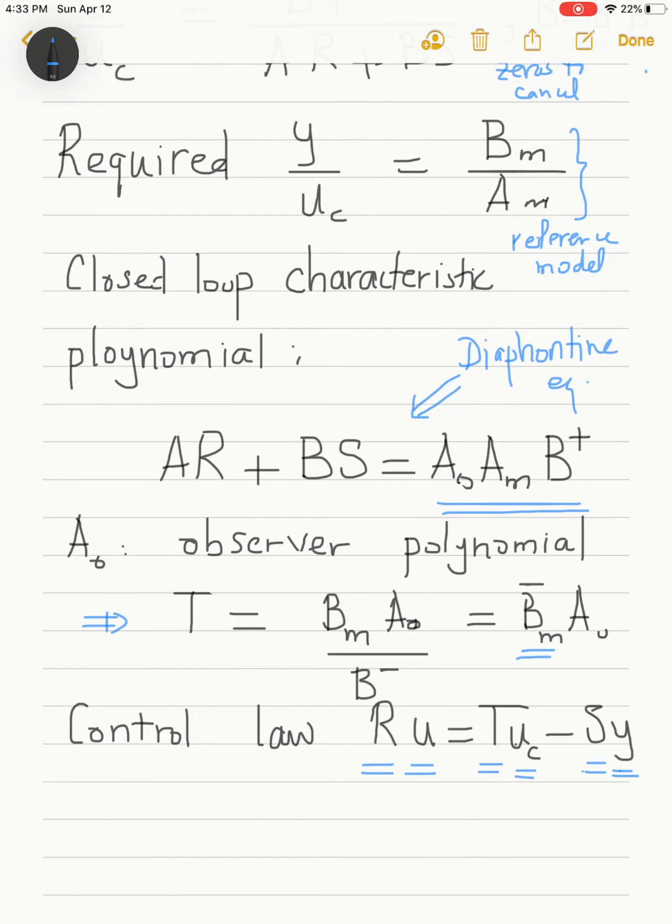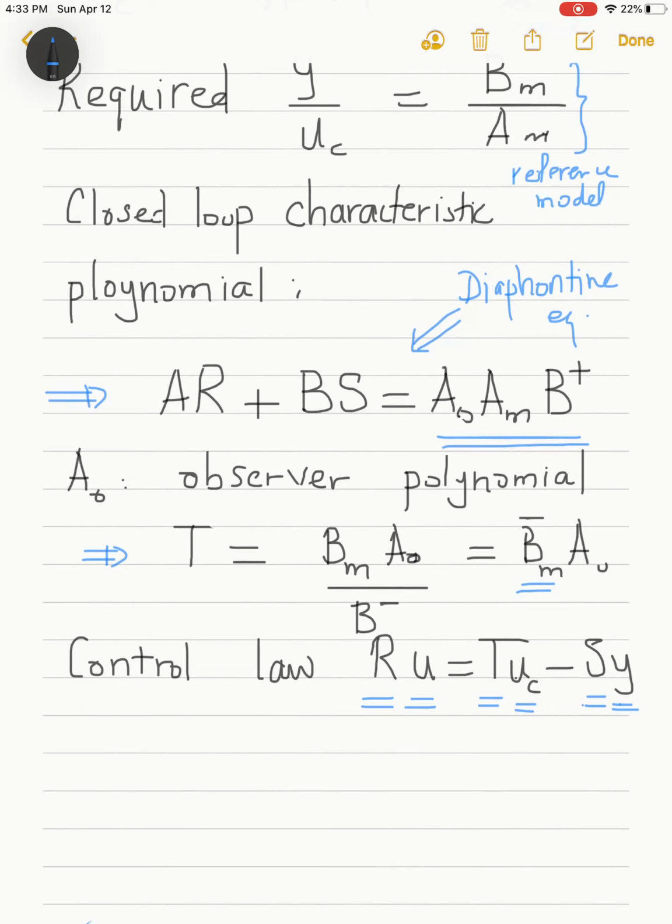Now our purpose is to see how we would use direct self-tuning regulators, which means how to rewrite the equation so that we can estimate the parameters of the controller directly using the estimator. So I'm going to start from the Diophantine equation. I will write R as R dash times B plus. We know that if we want to cancel a certain factor B plus, then it has to be a factor in R.